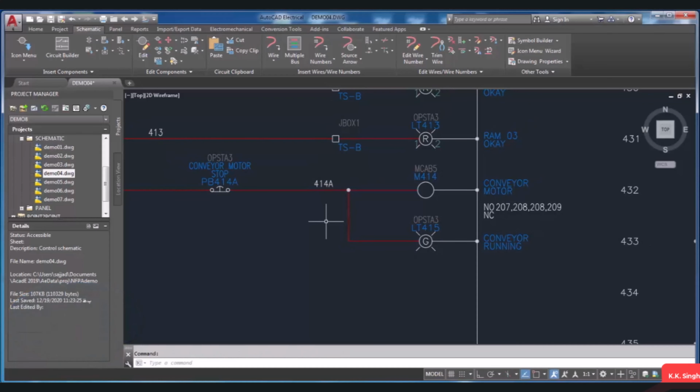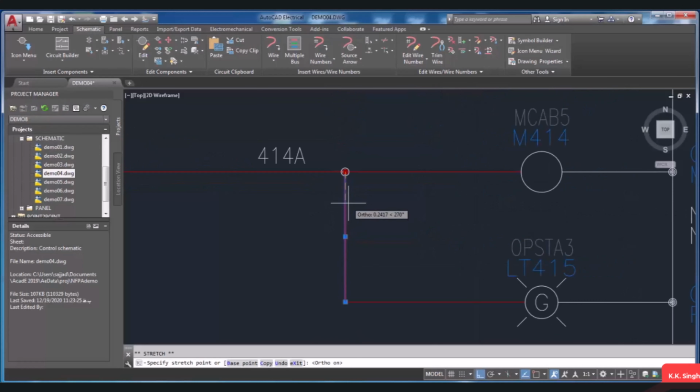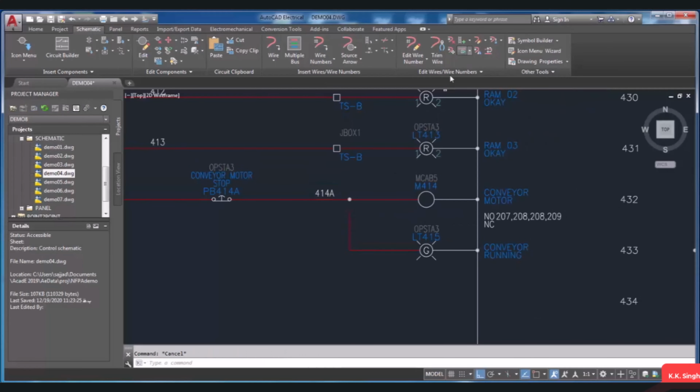To show you another example, I just want to cut this wire from the network and see the result in the wire trace. Therefore, I select the wire and I'm going to choose the disconnected wire here. I press A to show all segments and here you can see that this disconnected wire is not part of the selected wire, which means that this wire has been separated. This was the procedure of how to trace or check wires in a drawing.